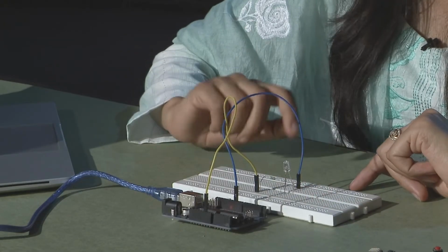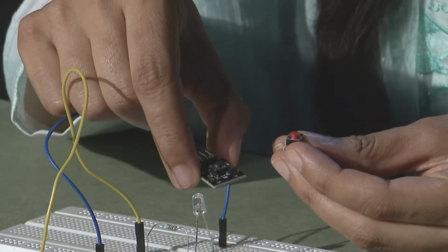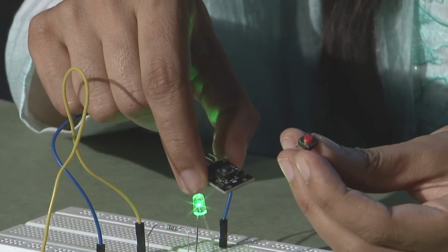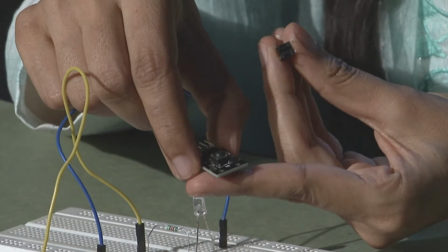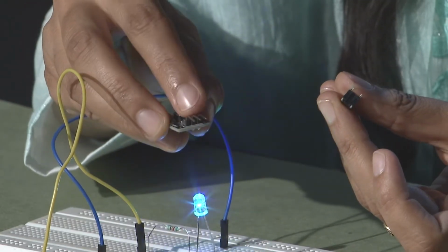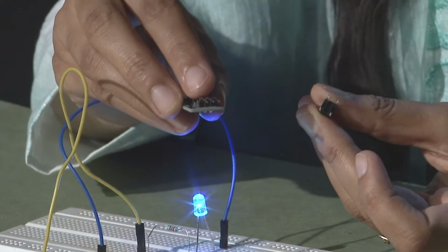Now we have one step ahead to go. Currently, we are using only one output device with this system. Now, we can use one input device as well. Here you can see I have two switches in my hand. Both of them are the same type. We are using a push button switch. Either you can use this particular switch with these 4 wires, or you can use a simple switch module which has these 3 wires directly for connection of your VCC 5 volt, ground as well as the signal terminal.